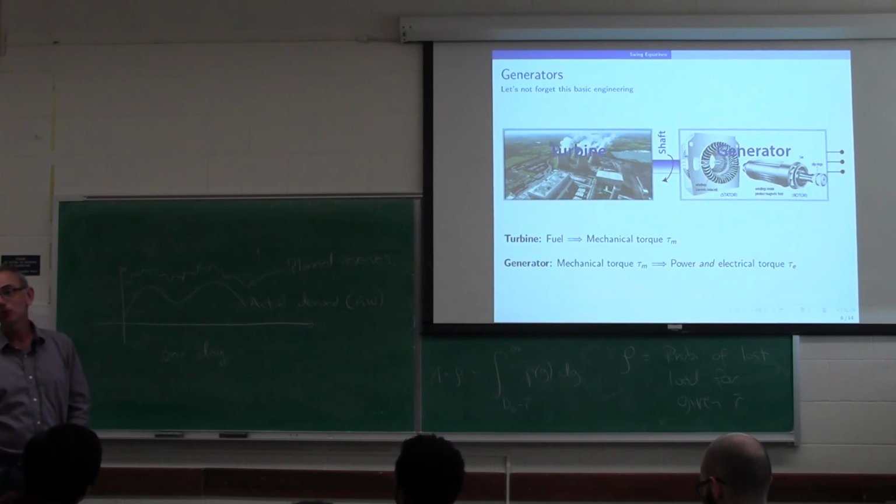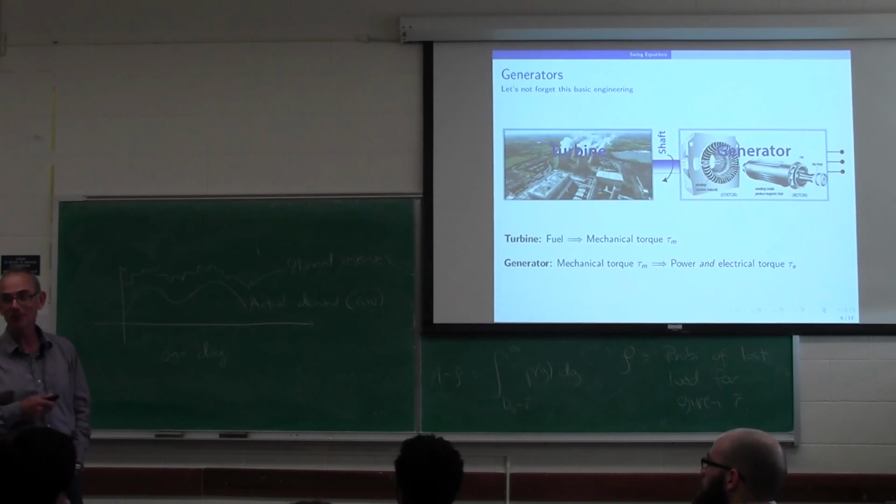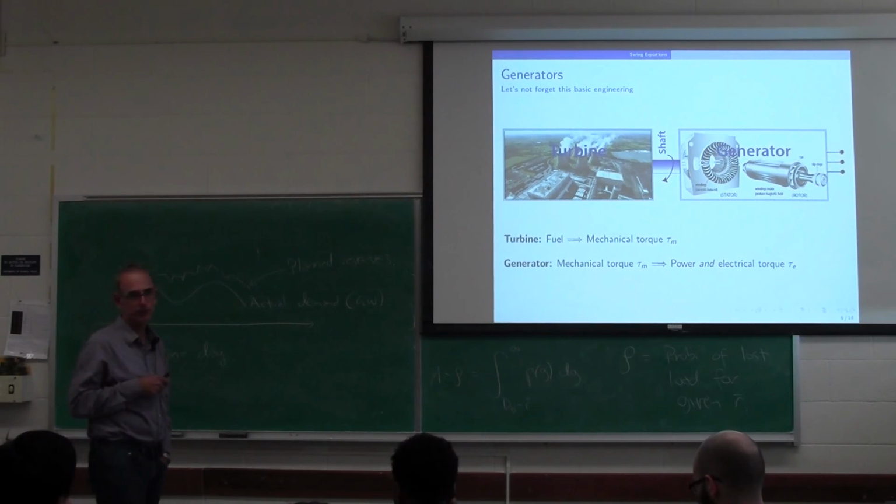And so Joe Chow at RPI has references there, but it's not in any books. And that's what GE says as well. But it's actually resonances inside these monster generators, and the super high efficient generators are very fragile in that sense, that they can break. And that's why they don't have as many of these super expensive high efficient generators in Europe or in India, and they're more robust to that.